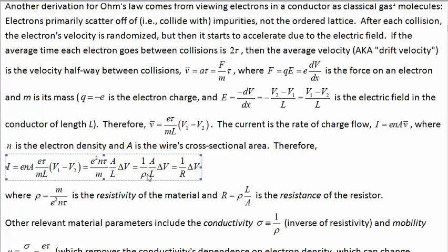And how does the resistivity of a conductor depend on things? Well, the resistivity increases with mass. It decreases with electronic charge squared. It decreases with the density of the electrons that are used for conduction, the conduction electrons. It decreases with increased time between collisions. So if you have a more perfect lattice or more conduction electrons available, other things equal, or imagine some magical material where the charge-carrying bodies weren't electrons but were something that had a higher charge, then those things would increase the conductivity, the inverse of the resistivity.